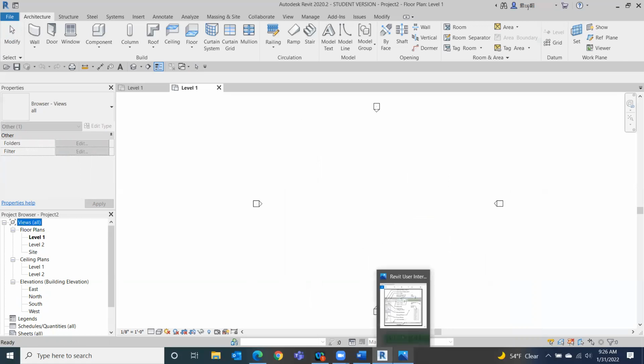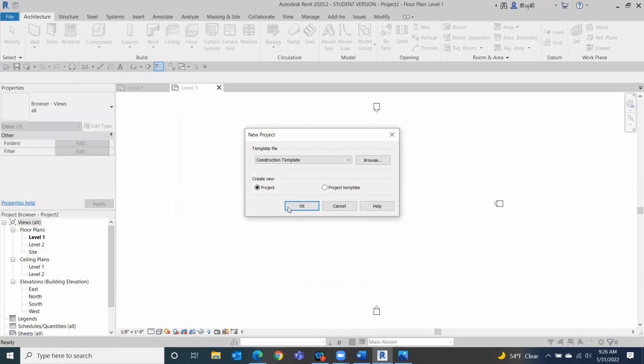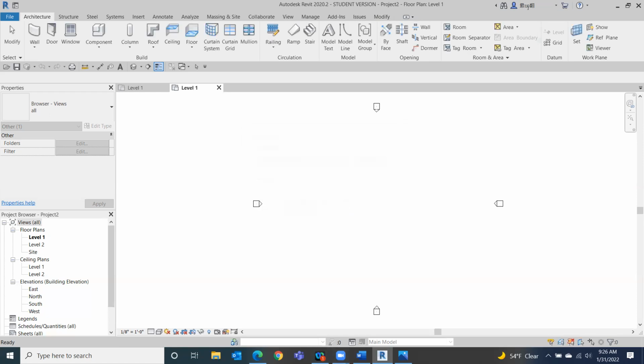I'm sorry, I had a question. Sure. When you say new project, template file, architectural template, it has a choice of create new project or project template. Which of those two options? Oh, good question. Definitely always project template, because you're not going to be creating a new one right now. So you mean like here? Yes, ma'am. We're always going to be using the default, go to project. Okay, just that default. This one would be if you wanted to create a new project template. A lot of firms will create their own project template, so it does exactly what they want it to do, but we're not going to create that for now. We're just going to use the default in Revit. Okay.